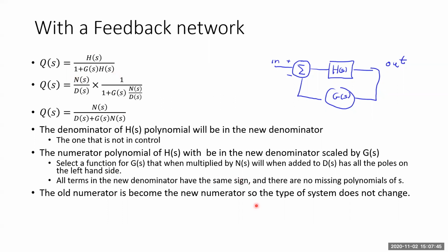Whatever the system was, the old system was out of control. It's either an integrator, an oscillator, or has exponential growth. But whatever the system becomes once it's in control, that numerator will give you a hint of what's going to happen. If it's a constant, with no term of S, it's going to be some kind of low passish function. If it has an S term, of course, it depends.